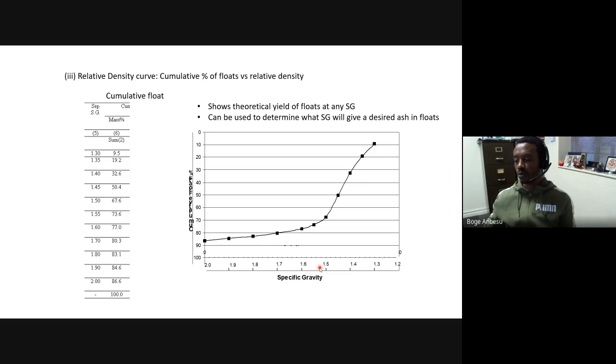Let's say I want to lose only 20% of the coal. Then you're targeting 80% in that case. So 80% recovery can be obtained if you use media of 1.7 specific gravity. So when you increase the media specific gravity, you are allowing more and more material to float. Okay. As you allow more and more material to float, with that, you are allowing more and more coal to float. Okay. So regardless, at 80% coal, you can achieve 80% coal recovery if you use a media of 1.7.